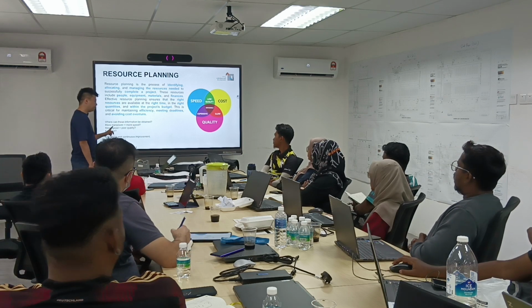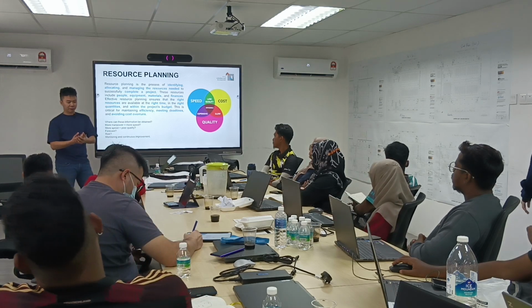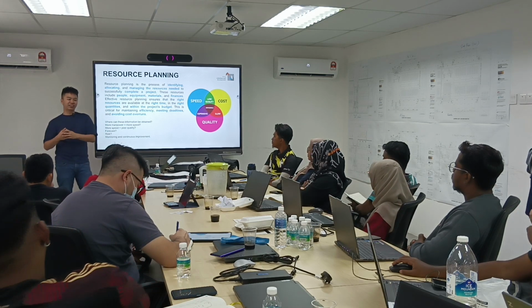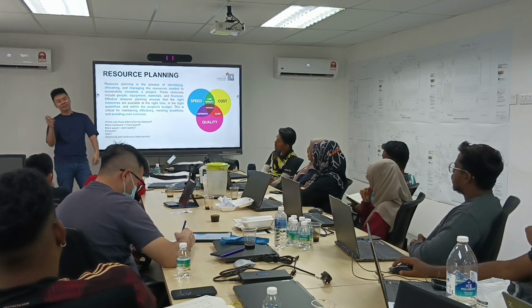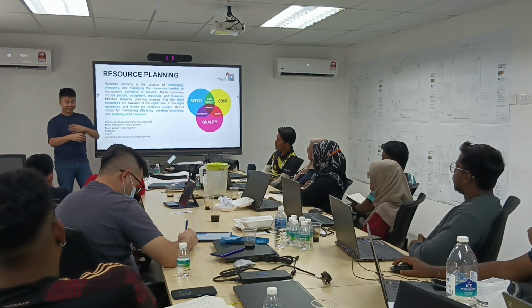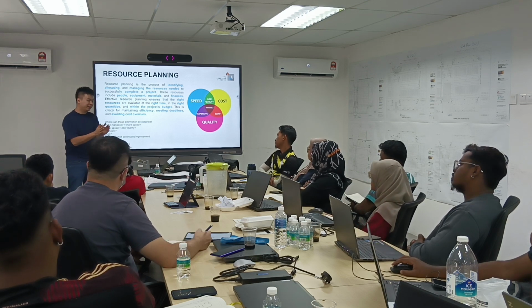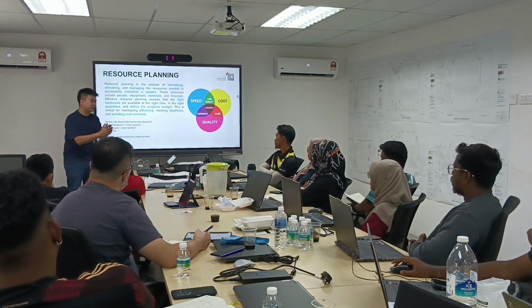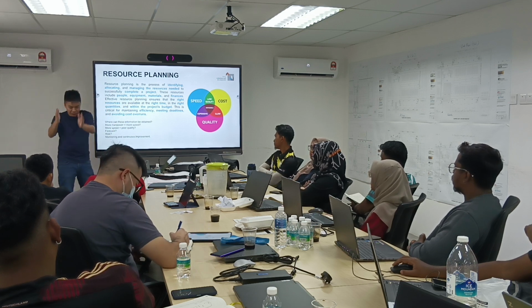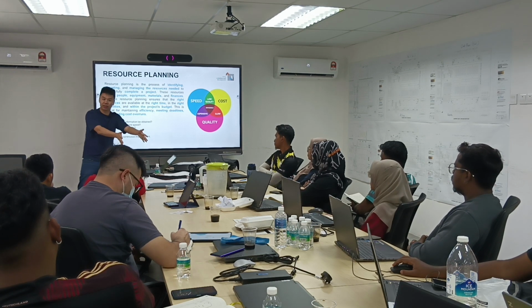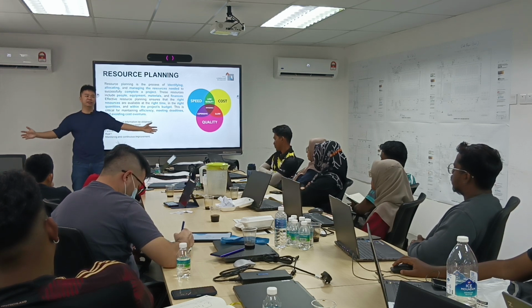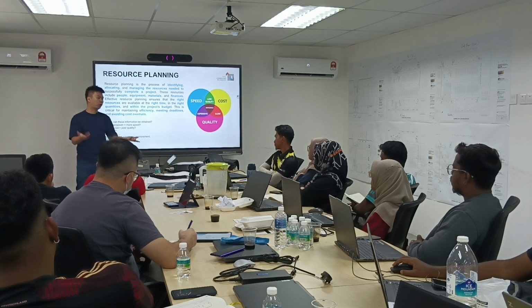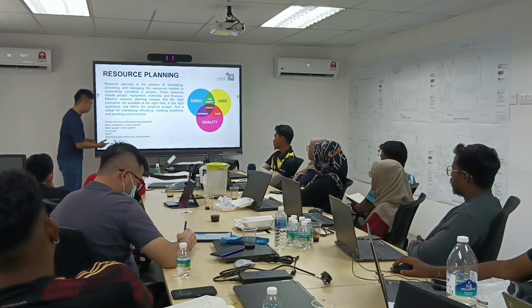Okay? Or another perspective is that, let's say you are in charge of Takang Jati, the excavation. They only have 4 excavators on site, right? I ask them to send in 200 workers. Do you think it's faster? No, right? So there is a lot of constraint. So you can't just base on manpower. You need to base on the whole resources plan. If you want to add manpower, then you need to add machinery. If you add manpower, you add machinery, you make sure the workspace is enough. If any of this is a constraint, no point. Yeah, you're just wasting money.